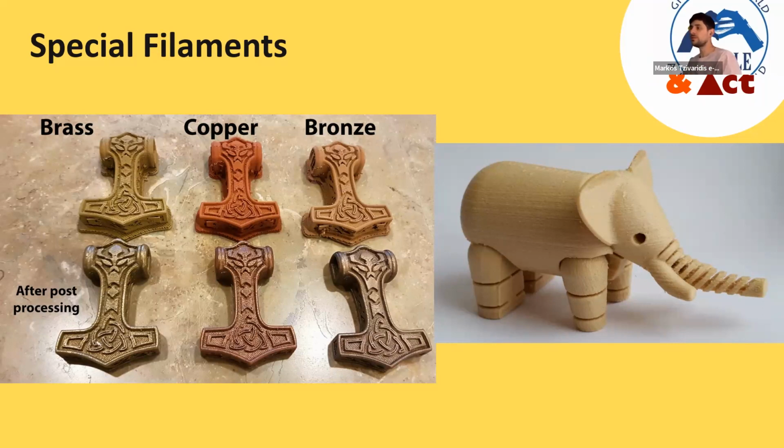How do you do it? When the print is done, it looks like clay, like the three parts you can see above. But then you can use some techniques to bring out the metal gloss. Now, a rotary tumbler, for example, is the easiest way of handling the finished part, but you can also use some fine grit sandpaper and polish your prints to your desired finish. The longer you polish, the better the shine, of course.